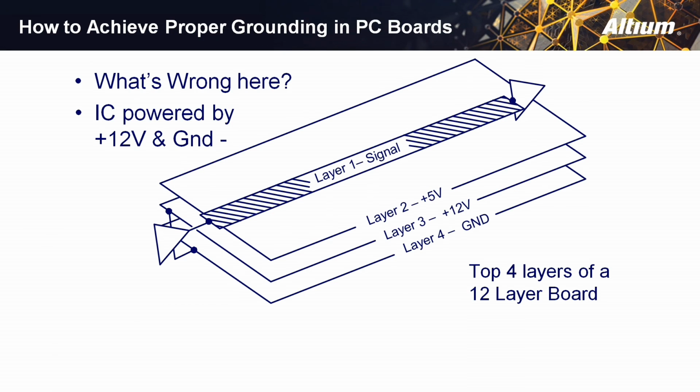When you're designing circuit boards, you really have to think about where you route. Be very, very cognizant of that. Only reference the power plane that generated the signals.